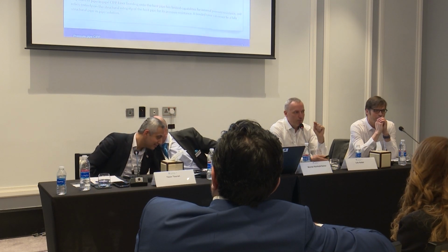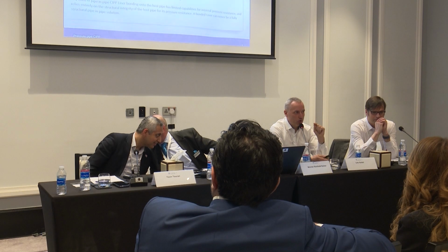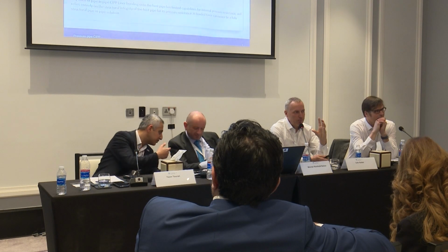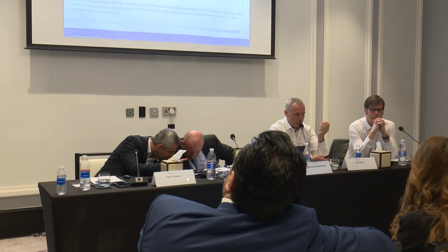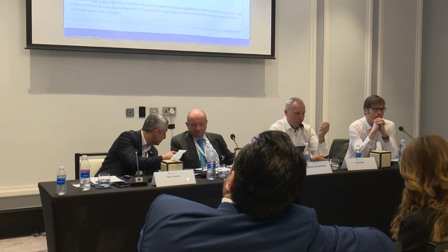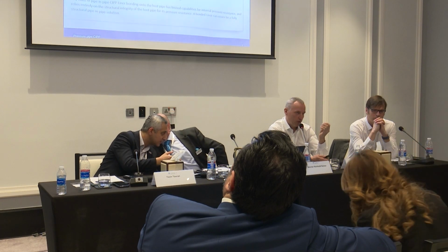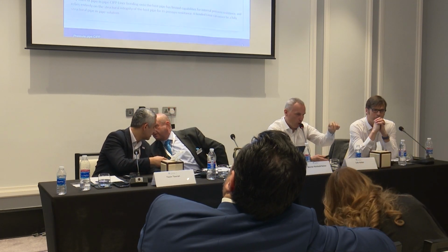Okay. So, bonding. Bonding is also very, very important because you put a new pipe in the ground. If you would bond the system onto the existing pipe, all your design assumptions and your engineering would not work anymore. I try to visualize it here. The second page will show you how that works. If you have the lining bonded onto the host line, that means there's no barrier. So all the peak stress, if your existing pipe is having a problem, a crack or a serious problem in the joint, at that point, only at that point, the liner will need to take all the loads. You see that on the red spot up there, visualized.